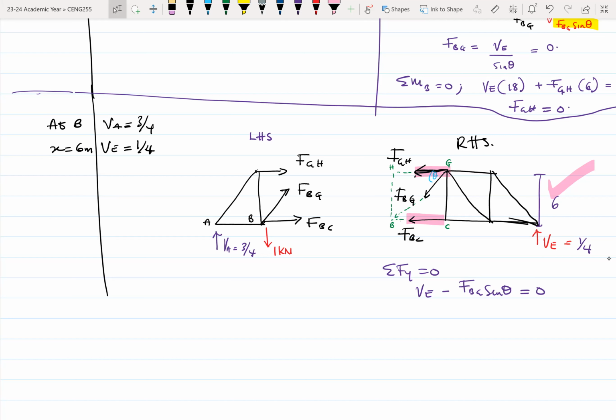So it's like we keep solving for the same thing based on the different positions of the unit load. The best method to use is the method of sections. You cut your truss whereby you can have at most 3 unknowns. Please take notes. If you have more than 3 unknowns in the members, it is difficult to do your analysis or your calculations in this case.